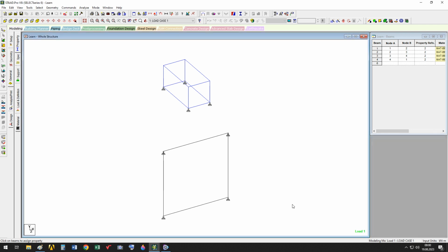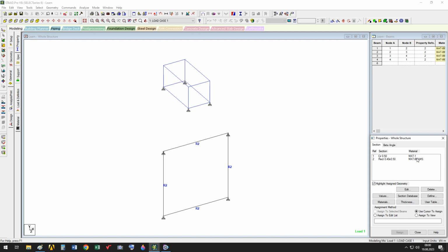Now, okay, the beam has cross-sectional property and material property. They are combined here and then assigned to the beam element. But the solid element has no cross-section. Its shape is already determined, obvious, clear, because it's three-dimensional. It's already there with its real dimensions.